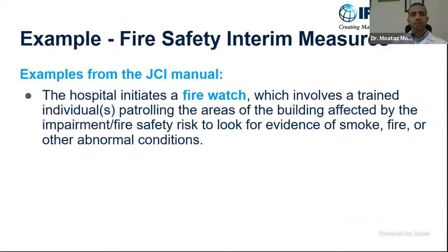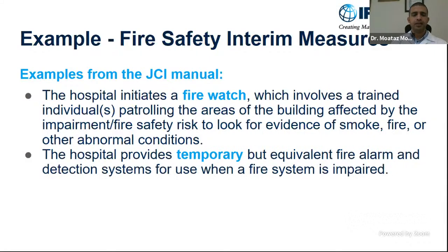What the hospital should do immediately is to start a fire watch, which includes an individual or a team who is trained on this process to patrol the areas that are of higher risk to get fire. For example, if you have any warehouse that includes many combustible material, this should be included in your fire watch patrols.